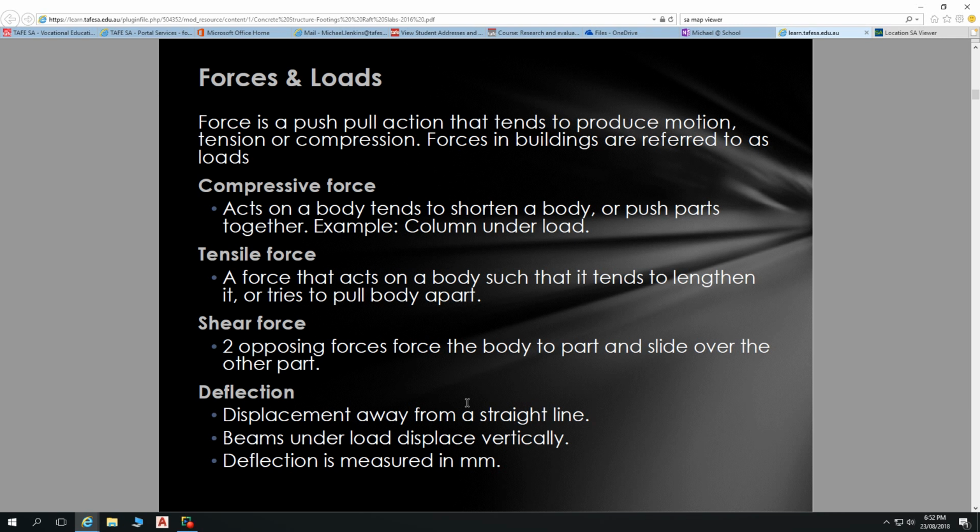The only load bearing walls would be this front wall and the back wall. Possibly there'd be some load from these hip ends as well with a hip roof. With a gable end roof, there's going to be no load, or imperceptible load, on those ends. All these other walls are non-load bearing, but if we're going to have bottom chords that deflect, and we're going to be fixing non-load bearing walls to those bottom chords inside the building, we need to have some accommodation for movement happening there as well.